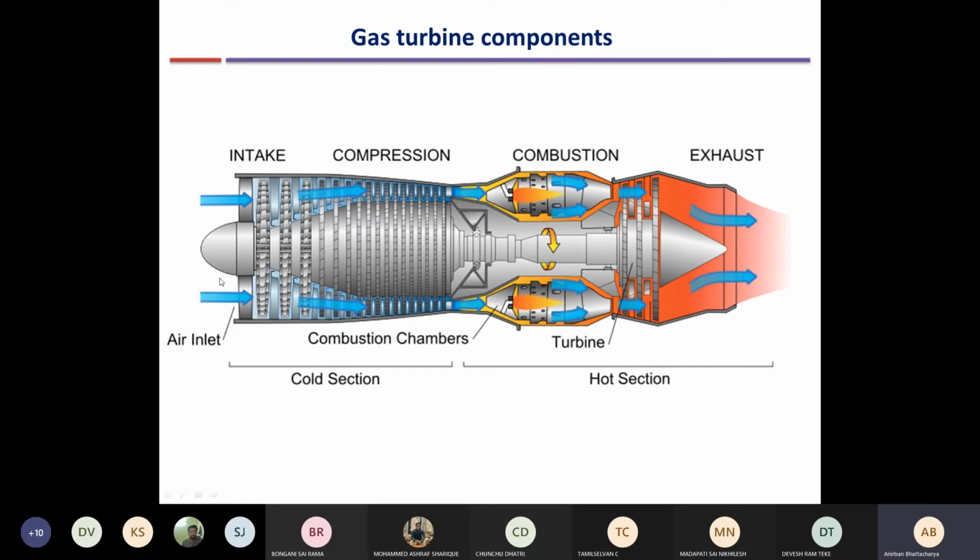which will be in front of the compressor, and the diffuser is actually like the opposite of a nozzle. So in the diffuser, the high velocity fluid undergoes transformation to a low velocity and dumps its kinetic energy to increase the enthalpy or pressure energy. So the pressure and enthalpy increase and kinetic energy is reduced. Then this fluid passes through the compressor blades, as you can see here. Because the compressor blades are rotating, they will increase the velocity of the fluid. Okay, after it passes through the compressor blades, the velocity of the fluid will increase.